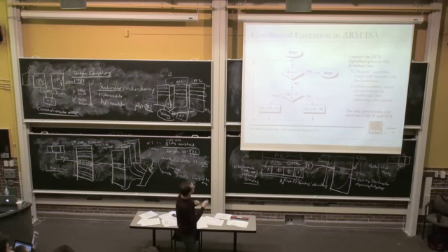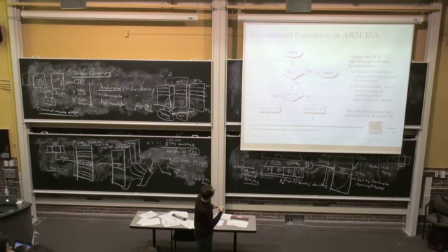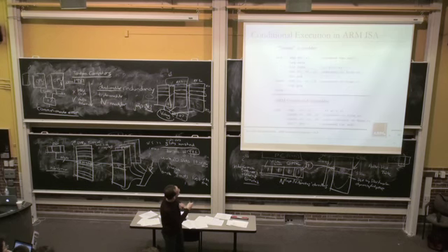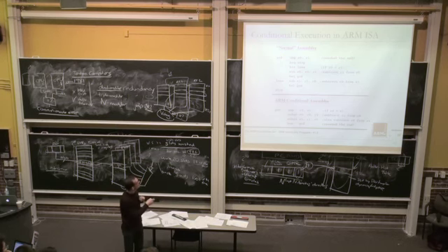From some of the ARM slides, this is some code that figures out the greatest common denominator, and they show you some code that you would get with the normal assembler, if you will. Normal assembler being assembler that produces normal branch code, and the ARM conditional assembler, which uses the conditional execution provided by the ISA.